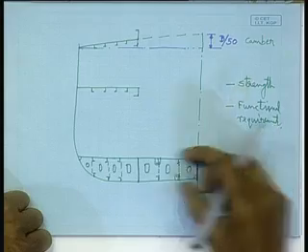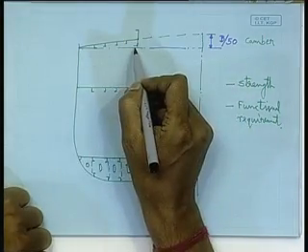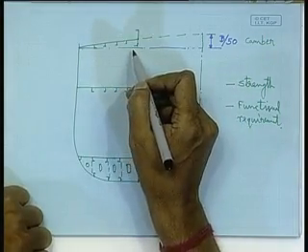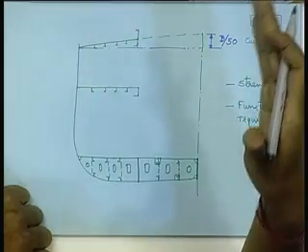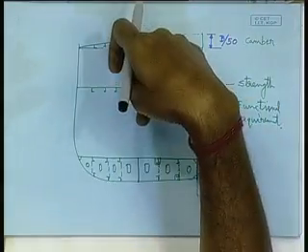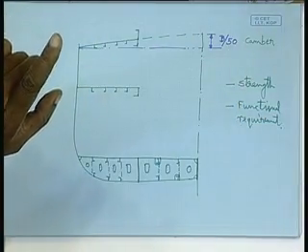Okay, so once this is done, my bottom shell is done, the double bottom. The deck, here we have shown the deck longitudinally stiffened. Now we have said that these longitudinals should have supports, because otherwise the length of the longitudinal will be from one bulkhead to another bulkhead, right.